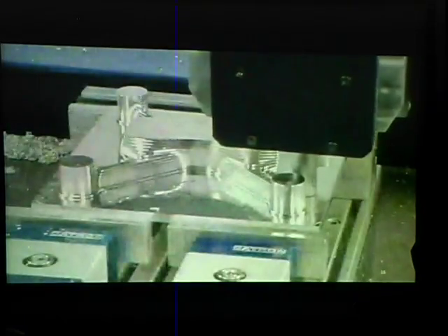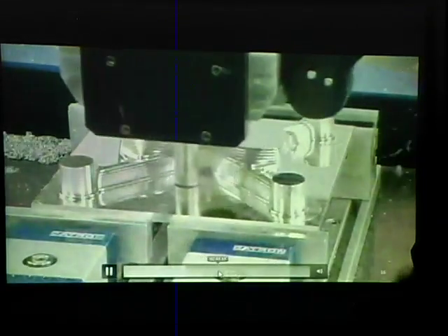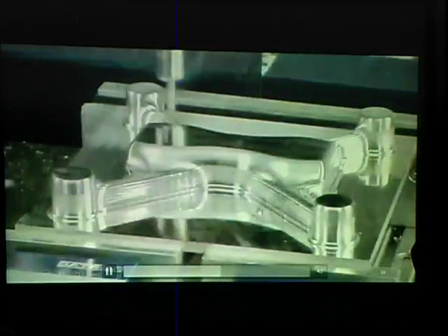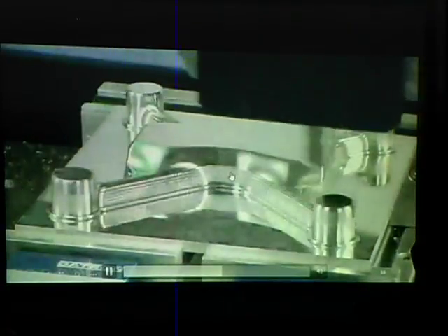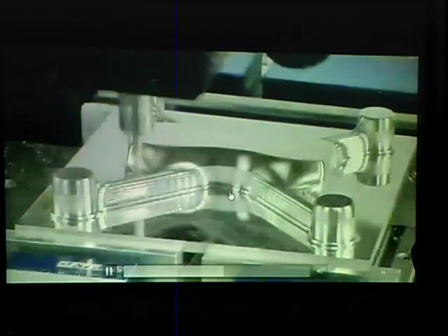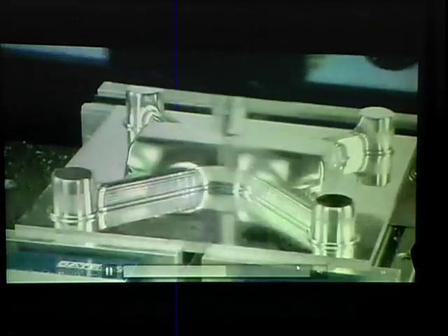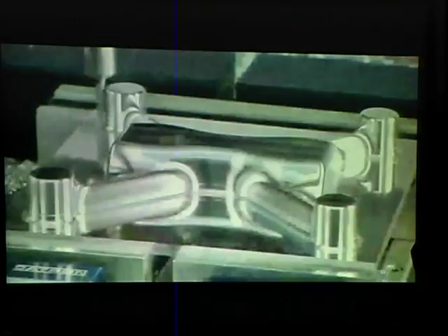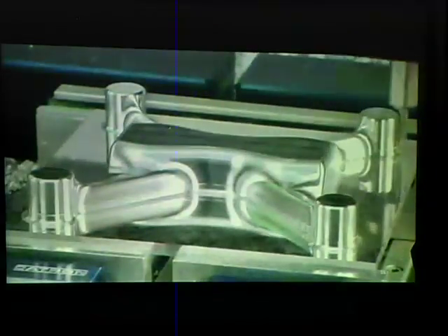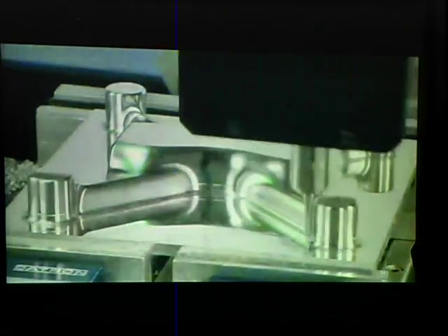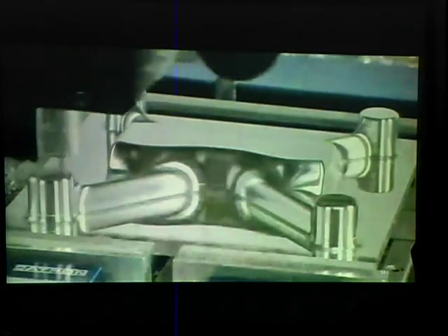And now it's going to come in and start profiling this in smaller and smaller steps. We're going to speed this up a little bit, and start smoothing out those shoulders. We can see it's taken those big step overs, those big step downs from the roughing stage, and it's making a nice smooth part out of everything. Eventually, at the very end, we get a fully finished part that looks like this. If we do it right, you can even sometimes avoid having to go in and polish this as you might in a typical injection mold to make sure that your parts release.